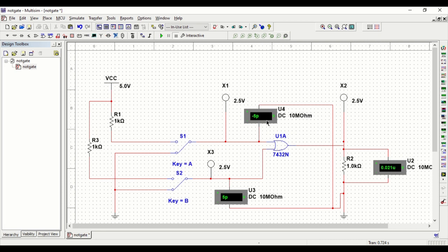And so we have just finished up building the OR gate. One last gate we're gonna build is the AND gate. And to do that, we're gonna do it as simply as just replacing the part. Right click, replace part, and as we do the replacement, we can change the OR gate into an AND gate. So right click, replace part, and we're going to have now an AND gate, which is a 7408. And really, this is all we need to do to make the AND gate.